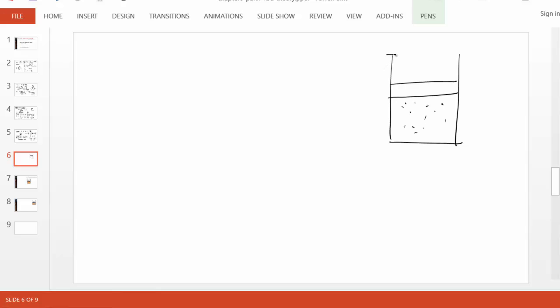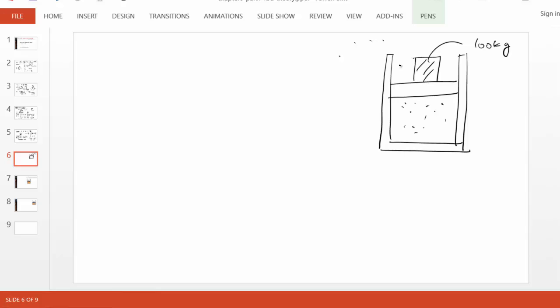Basically, we'll do this so many times, we'll get used to this. There is no friction. We'll assume there is no friction between the piston and the cylinder, so that the piston is free to move. And suppose we put a mass of 100 kg on this piston. So the benchmark, by the way, atmosphere outside has a pressure, and we'll typically call it P0. And a benchmark for pressure could be P0, which is about 100 kPa.